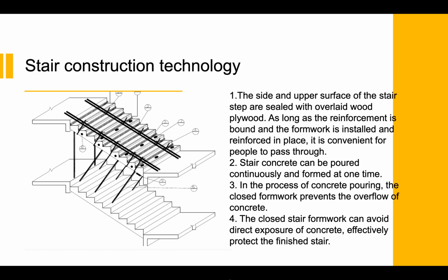2. Stair concrete can be poured continuously and formed at one time, which can save labor. 3. In the process of concrete pouring, the closed formwork prevents the overflow of concrete, can save materials and labor, and improve the construction speed.